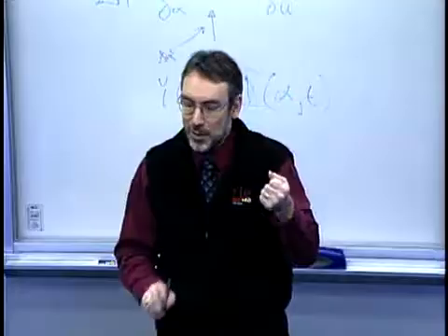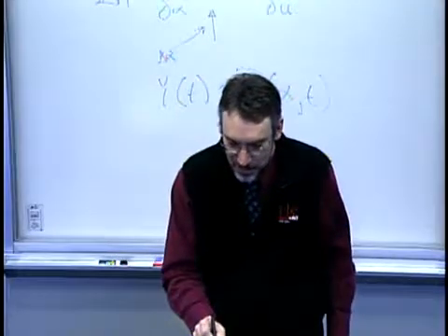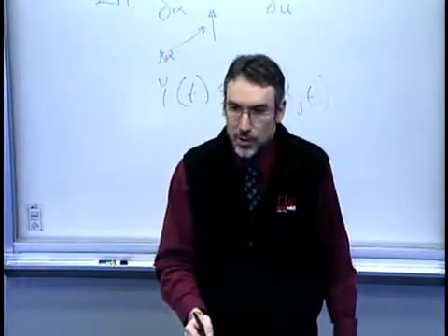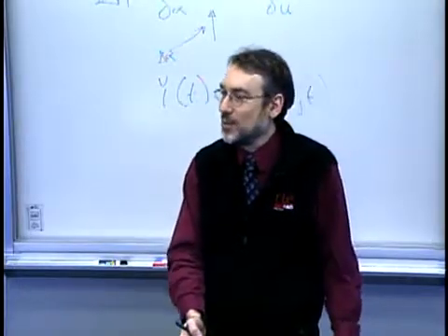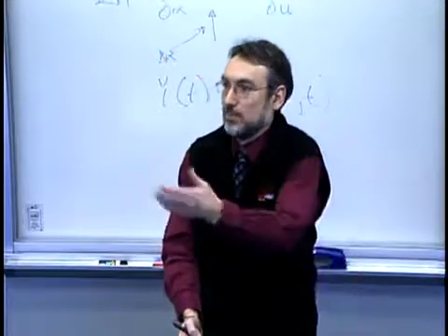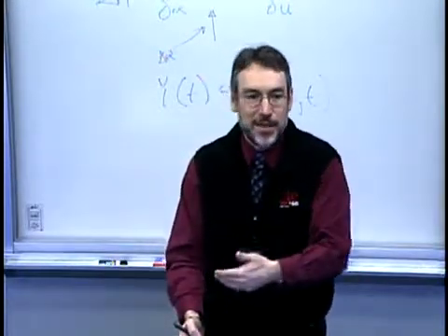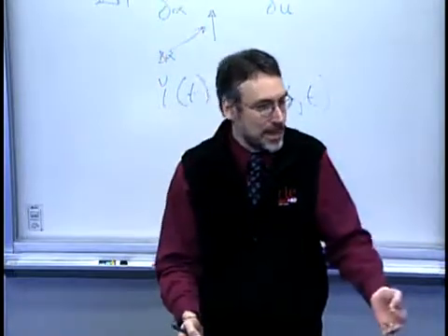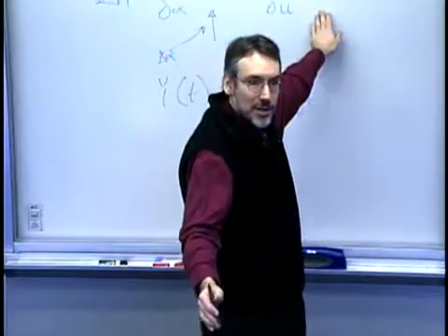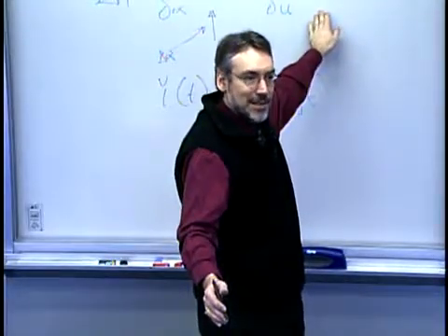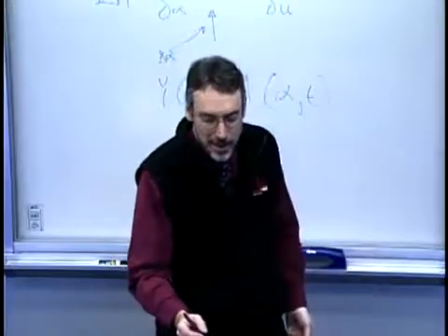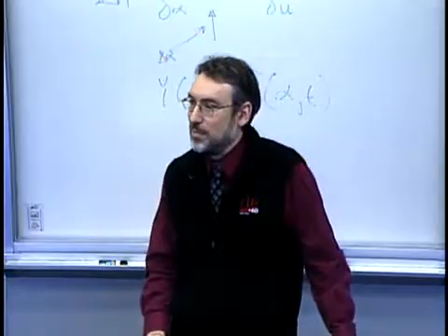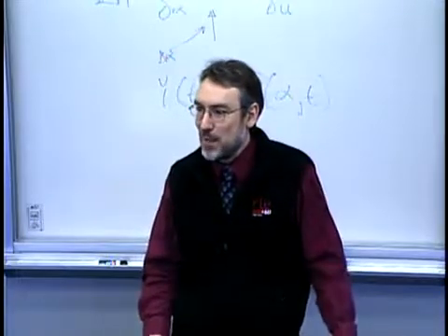And the natural occurrence is that over time, as you have learning about your process and manufacturing system, you're generally squeezing out these deterministic sources, right? It was repeatable, systematic, and therefore you can come up with strategies either to eliminate it or to compensate for it. Maybe you have a control strategy that recognizes that source of variation and keeps squeezing it out. And what you generally are left with are these random components, hopefully in a very nice narrow band.